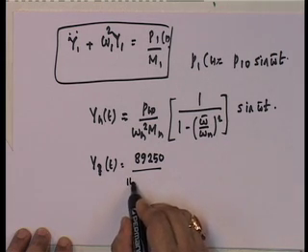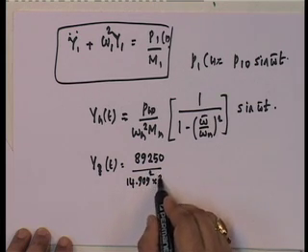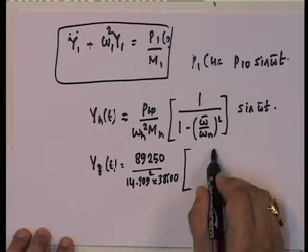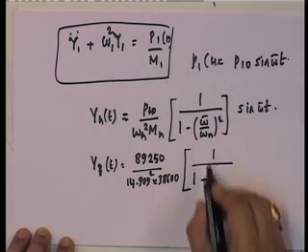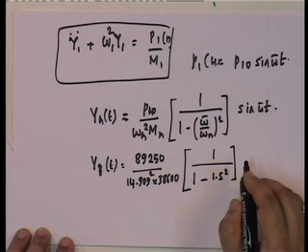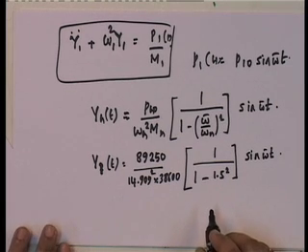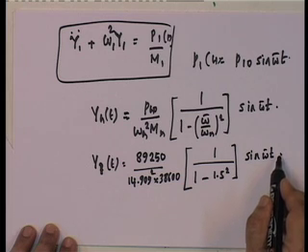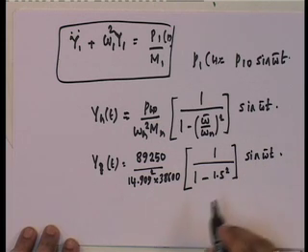So, that is 14.90 into 38.60 all upon 1 minus, now if you look at it, omega bar upon omega 1 is 1.5, obviously that is how we have done it, into sine omega bar t. Because this is an undamped system, therefore it will directly have this.